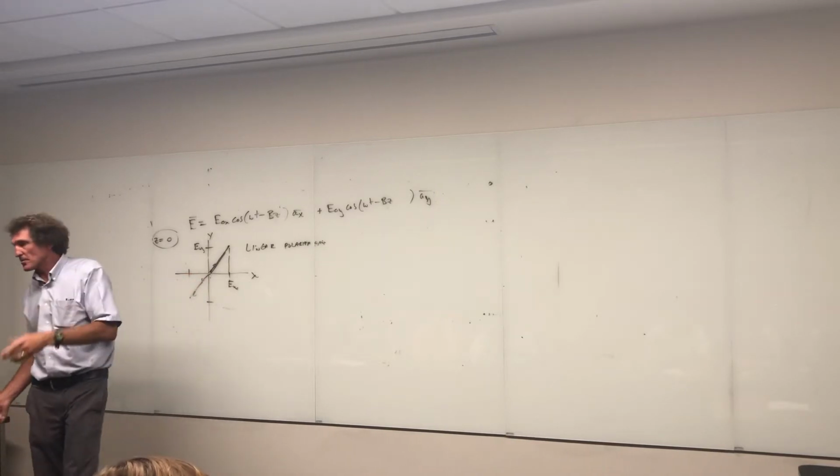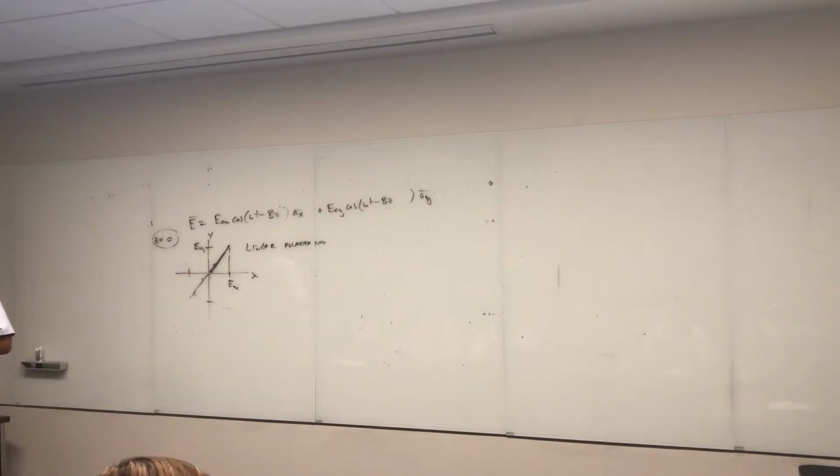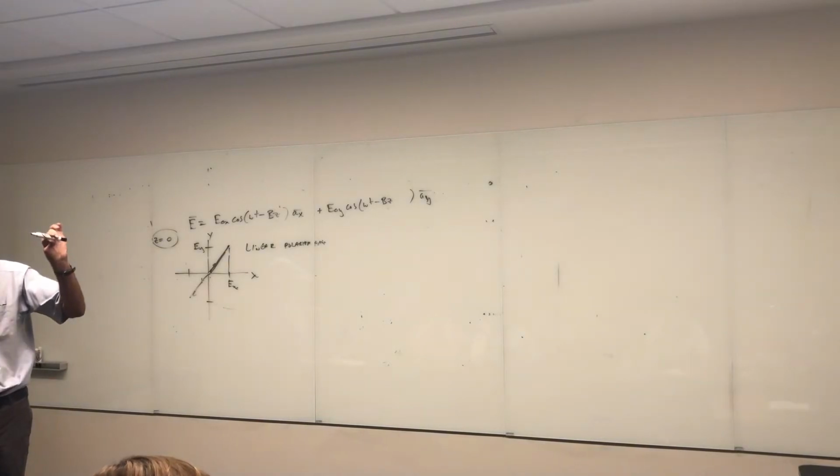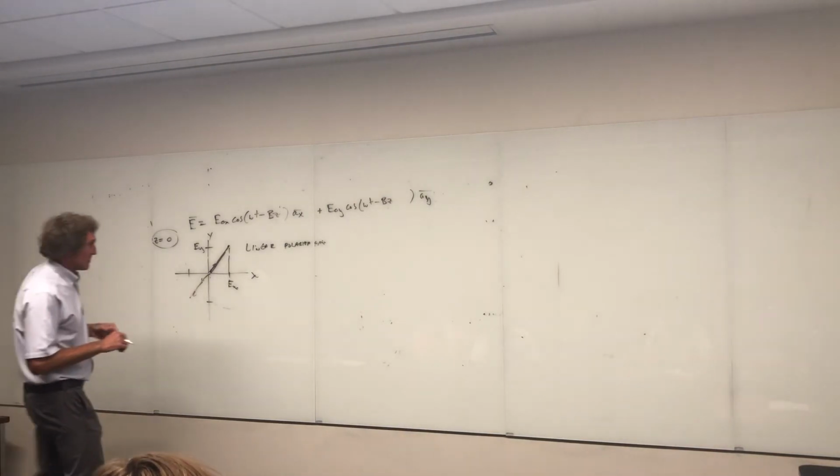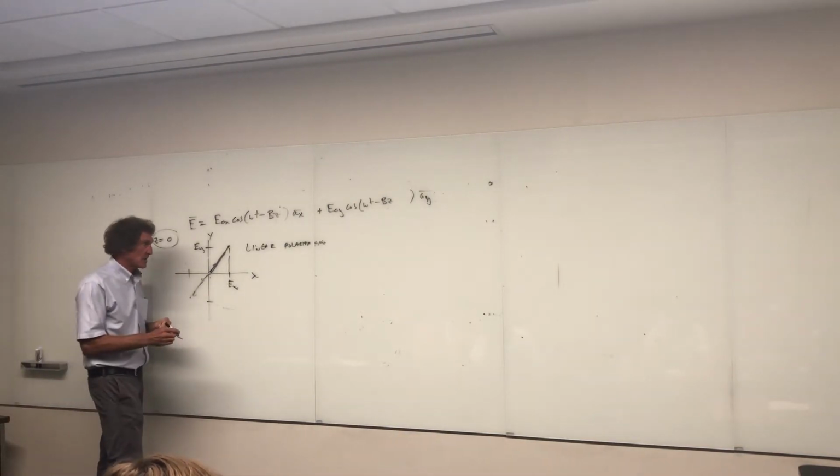That's the way in radar you talk about things, general antenna engineering. They want to know if your electric field's coming off horizontally or vertically polarized. That's all they want to know, for a lot of different reasons that you'll see in time, the reflection coefficients and other things that depend on it.